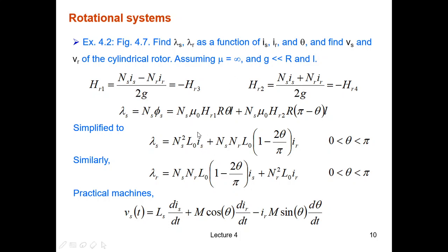It's sinusoidal with respect to time, because your current IS here is a sinusoidal time function. So this component is sinusoidal with respect to time, and when you have a proper air gap, then at a steady state, at a constant speed, the sinusoidal variation in space will convert into a sinusoidal variation in time.